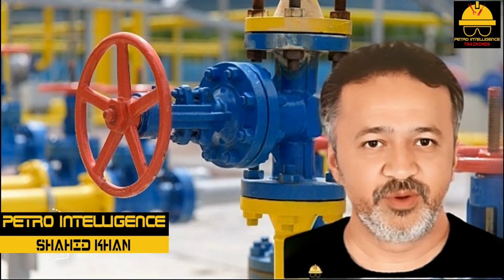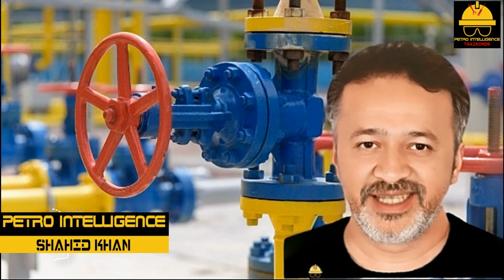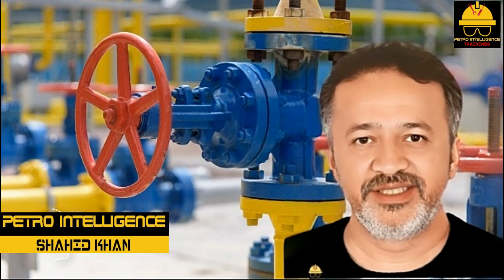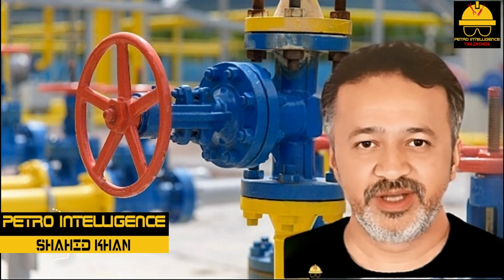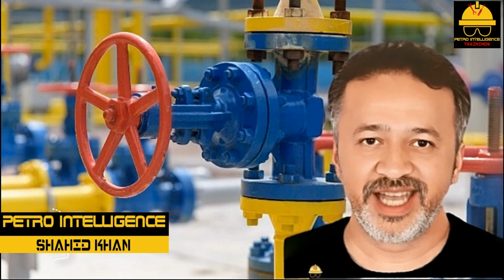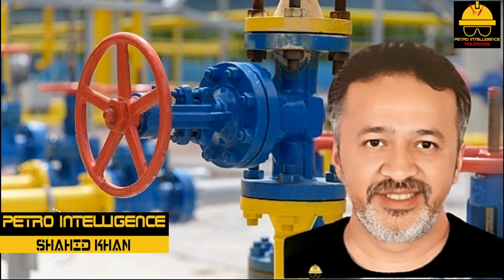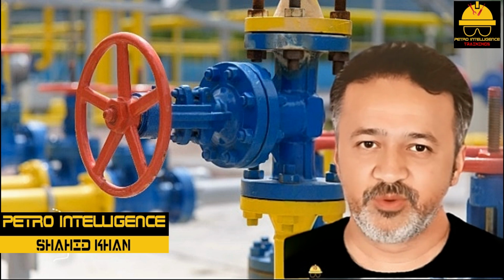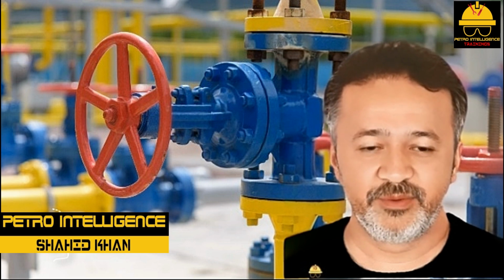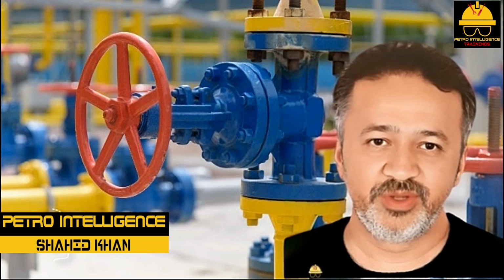Rising stem and non-rising stem. The stem on a gate valve comes in two designs, rising stem and non-rising stem. Located at the top of the gate valve is the handwheel. The handwheel is attached to a bushing, which is attached to the threaded stem. As the handwheel is turned counterclockwise, the stem in the center of the handwheel rises. As the stem rises, the gate is lifted out of the valve body, allowing fluid to flow.